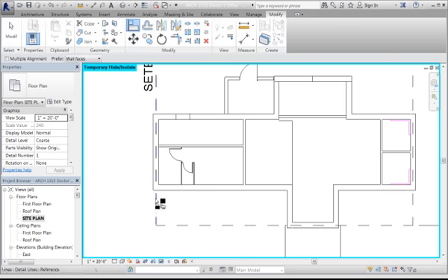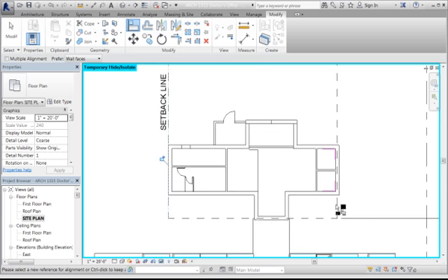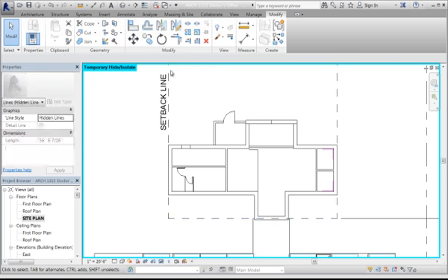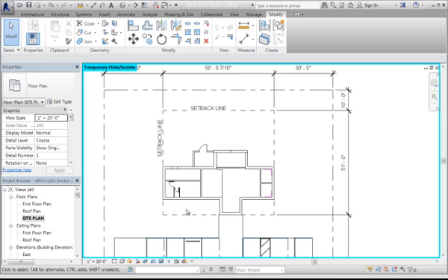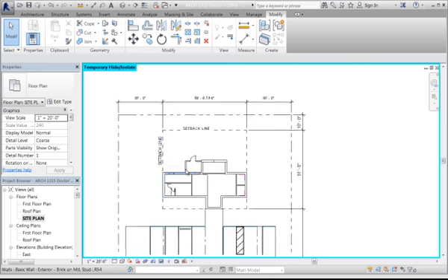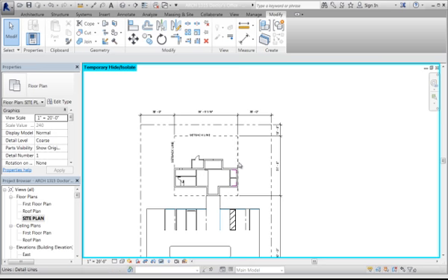I'm just going to do this. Just going to squeeze it in. Of course, you can't do that because your plans have certain dimensions. But let's see, align. Okay, so now if your building is on the setback line, then you don't necessarily have to dimension that edge. But if it's away from the setback line, then you need to dimension all 4 edges of the building, okay?